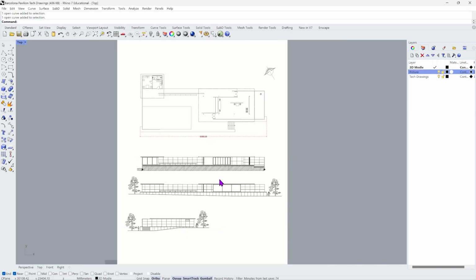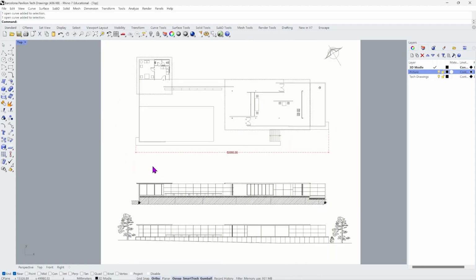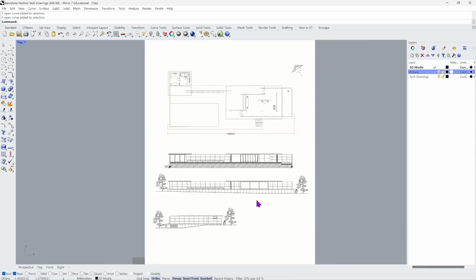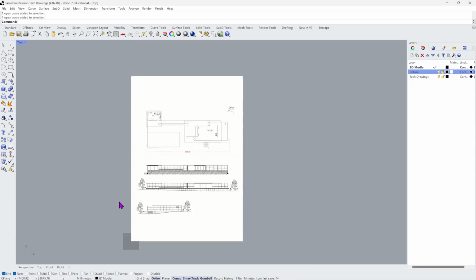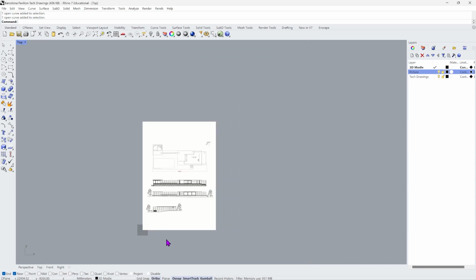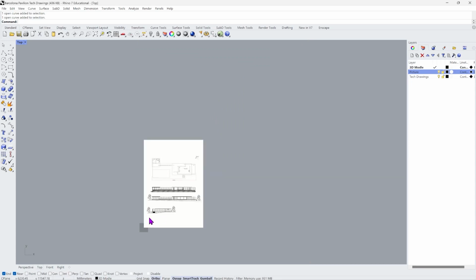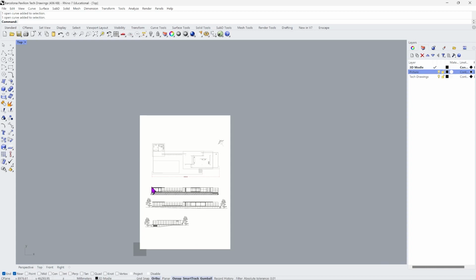So what is left to do is we need to trace this floor plan before we start actually going into 3D modeling. First things first, we need to make sure that we always work in 1:1 scale, and as we have an infinite canvas in Rhino, we can always have the benefit of working one-to-one scale. Always try to follow this rule. Try to work in one-to-one. You can always scale it down if you need to, or scale it up.